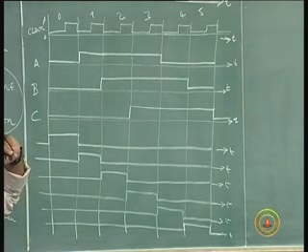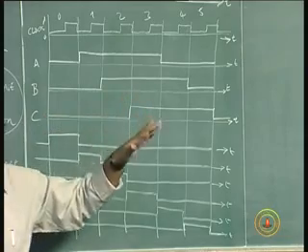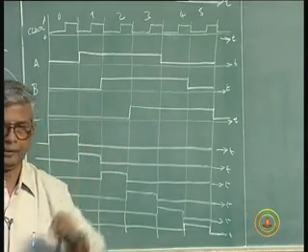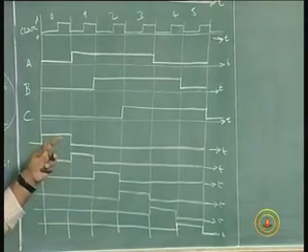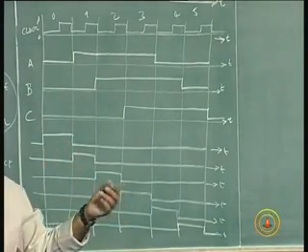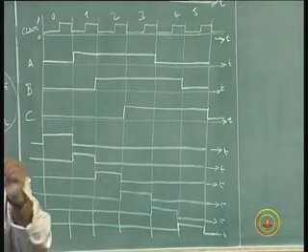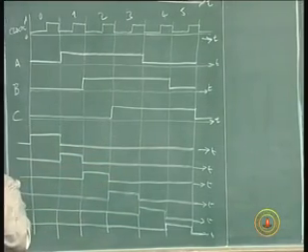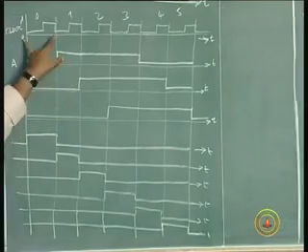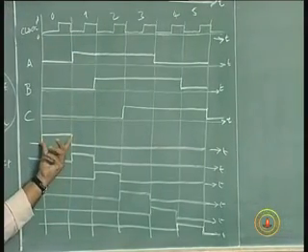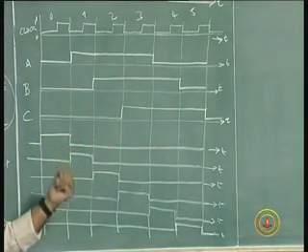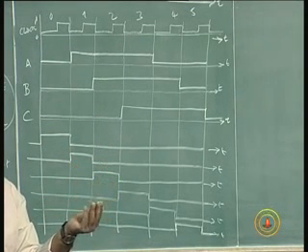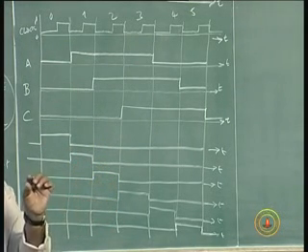I can have them on for half the clock period and the other half the clock period they start disappearing. Instead I want a clock with 6 phases, but each duration should be such that I have 6 LEDs or 6 lights which should each be turned on only for one clock period, the original clock period. That means I want something to be on for this period alone and off for the rest of the period. It can be a motor, it can be a light, it can be something which you want to just activate for this clock period.